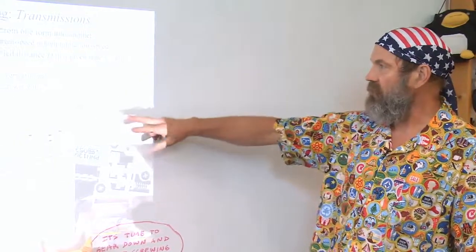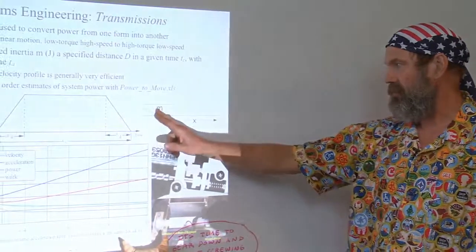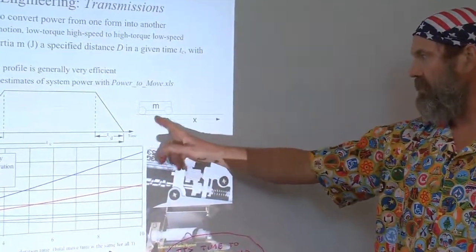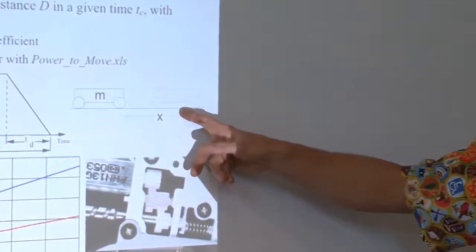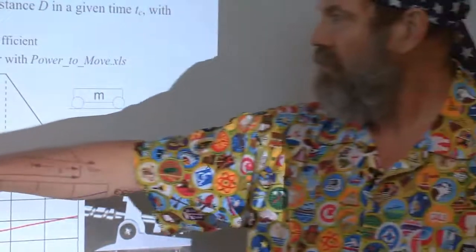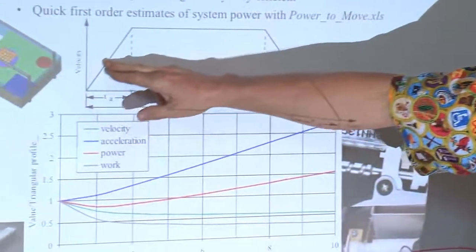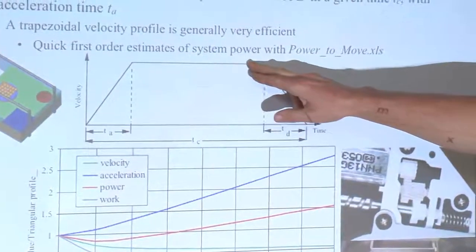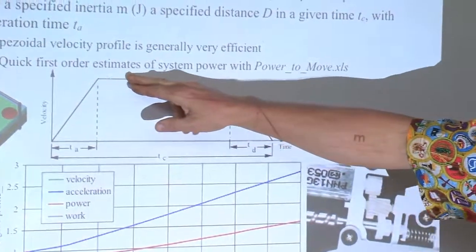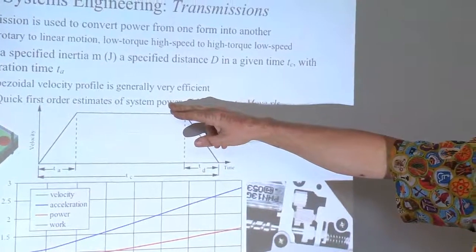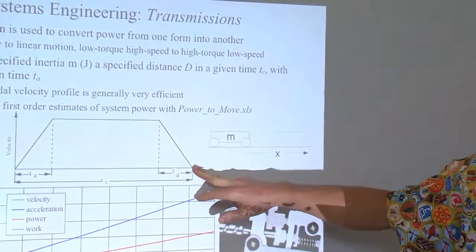Now, let's assume you have a car that's here, a little vehicle or shuttle on a machine. You go from here to here. How do you do it? Normally, you speed up, come to some speed, and move across at a constant velocity, for example, where you're doing your process of cutting or whatever your machine is doing, and then you have a time to slow down.